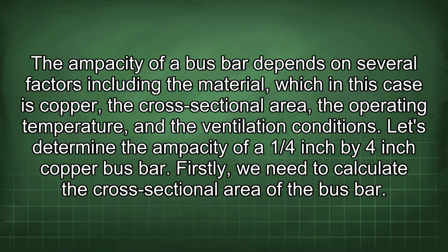The ampacity of a bus bar depends on several factors, including the material, which in this case is copper, the cross-sectional area, the operating temperature, and the ventilation conditions. Let's determine the ampacity of a 1/4 inch by 4 inch copper bus bar. Firstly, we need to calculate the cross-sectional area of the bus bar.